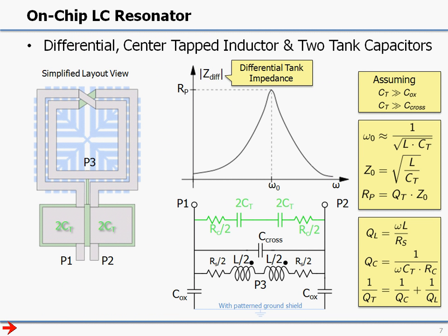Now that we have an inductor, we want to make a resonator, so we take maybe some fixed capacitance and we put it in parallel with the inductor, and electrically now we get this diagram here. Note that we will focus on the dominant components, the inductors as well as these two capacitors, and we will assume that the parasitics are small enough. At that point, we get an electrical resonator which has an impedance as a function of frequency, which we see here.